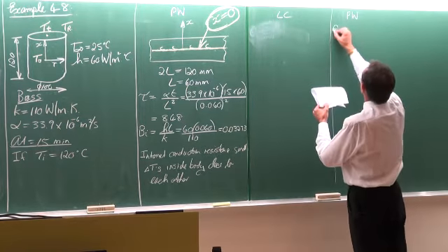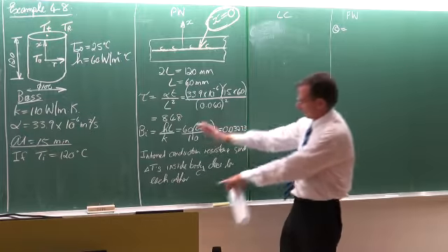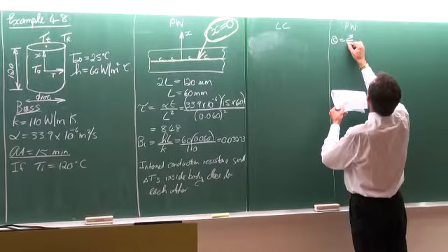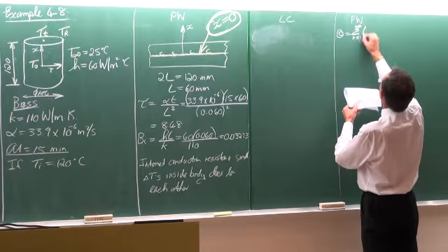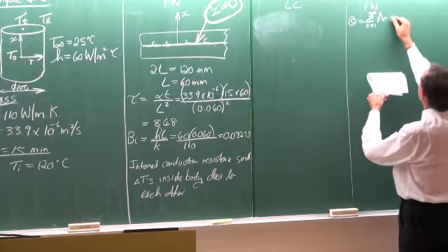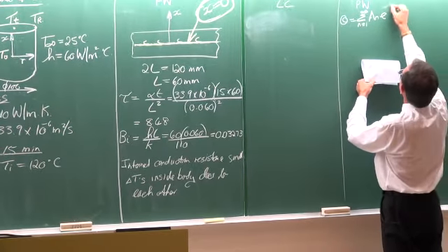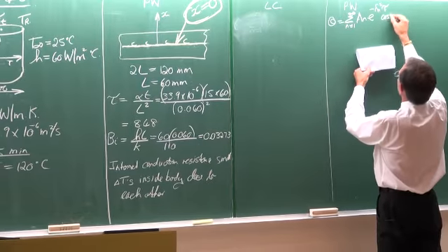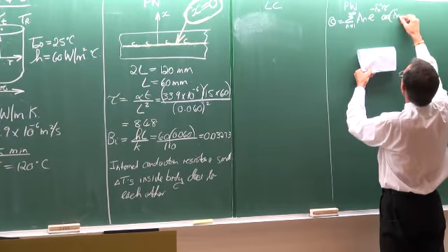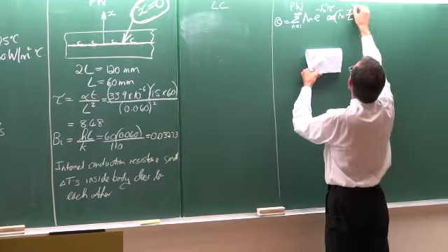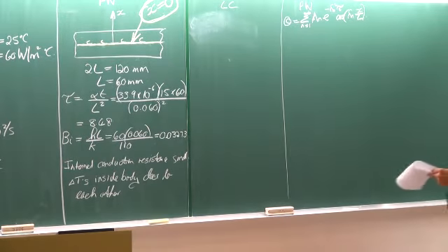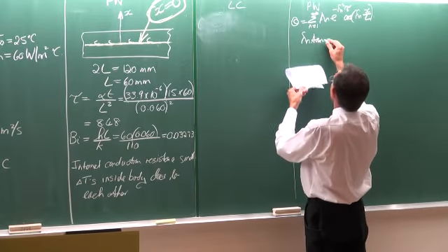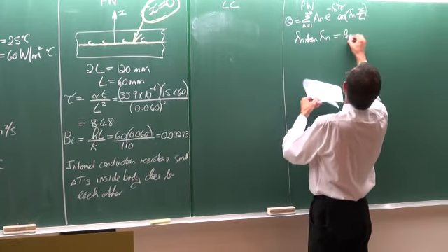Yes, we are still busy with going down on this side of the column. So the non-dimensionalized temperature is the sum from n equal 1 to infinity of a constant, and I'm going to write the constant down just now, e to the minus lambda n square multiplied by tau, multiplied by the cos of lambda n multiplied by x divided by L, and where the roots are lambda n multiplied by tan lambda n is equal to the Biot number.